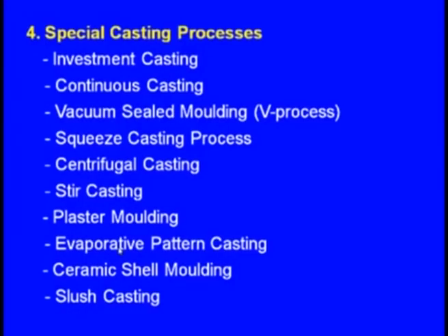Again, this pressure die casting is subclassified as the cold chamber pressure die casting and hot chamber pressure die casting. In the cold chamber pressure die casting, the furnace is away from the machine, whereas in the hot chamber pressure die casting machine, the furnace is an integral part of the die casting machine.